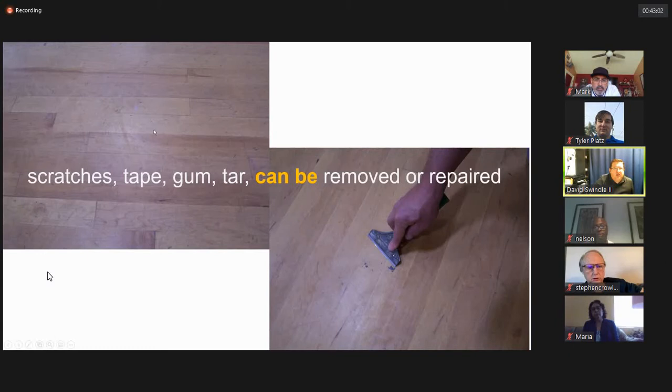We are not sanding the floor. We're simply prepping it so that the next coating will go on. We're getting it as clean as possible, removing any scratches that are in the coating. But the wood itself, if the scratches have gone into the wood, we will not be able to remove them through normal restoration. Those have to be sanded out, which involves drum sanding. And a lot of times you deal with a certain amount where you say, okay, it's at the point it's everywhere, I have to sand it. But you want to really do that as few times as possible. I've seen gym floors last for 50, 60 years, longer even than that.